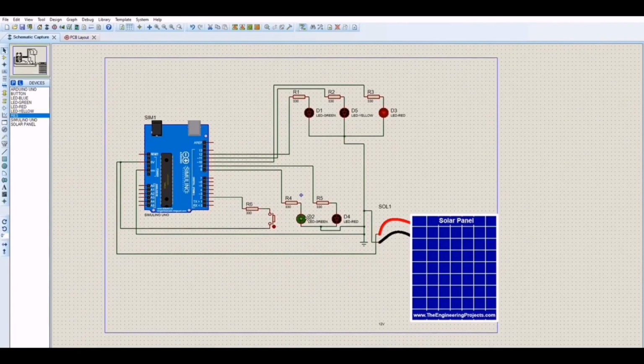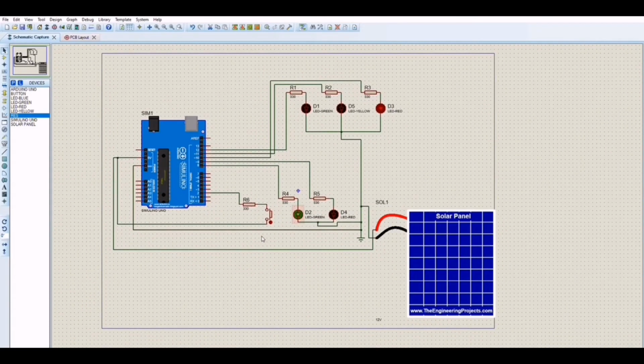Based on the coding that is made for this traffic light system project, the input required for the system to function is when the person pushes the button at the waiting area. The traffic light on the car side will turn from green to red for 2 seconds, and the LED for the pedestrian will turn from red to green to allow the pedestrian to cross the road for 15 seconds.